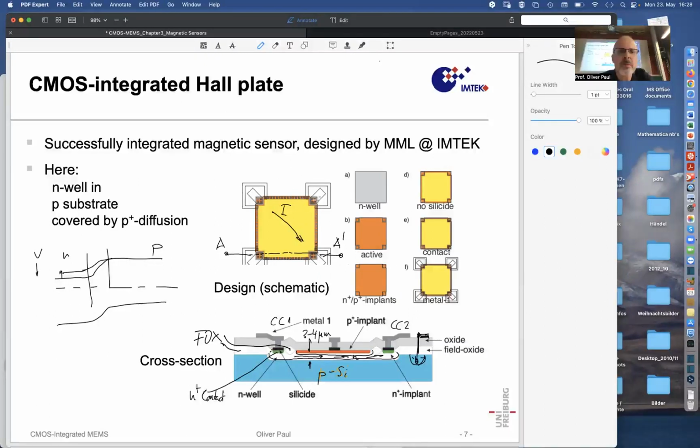And what you see from top here now is, let's say, the contact of these corner contacts of the N-well. They stop here, and then there are also some rims, some contacts around, that make sure that the reddish region is contacted everywhere on every side. This continues here, and this continues here also, and this is of course ended here.